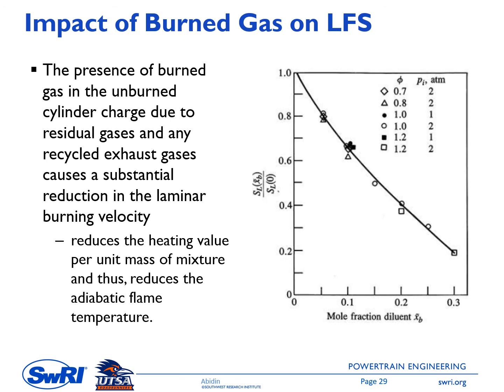The figure on the right side shows the impact of the burn gas on the laminar flame speed. We have the laminar flame speed normalized by the laminar flame speed without the residual, so when it is 0, it means it has no residual, no burn gas.